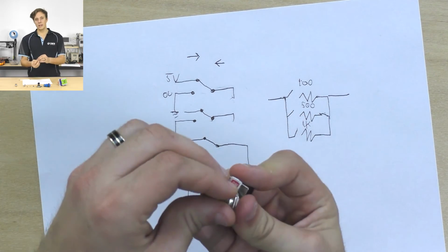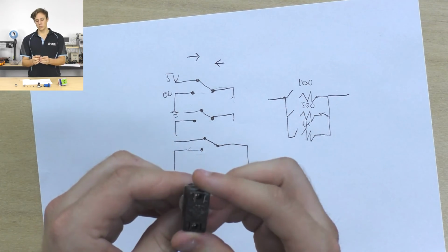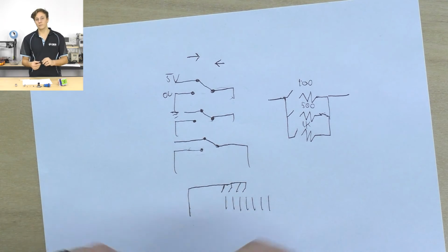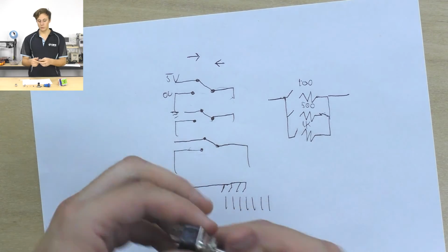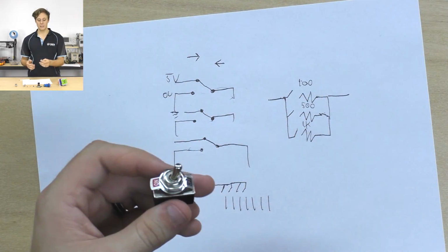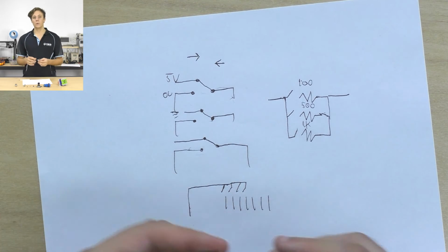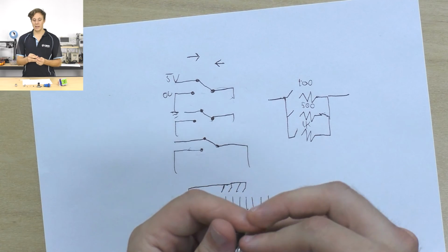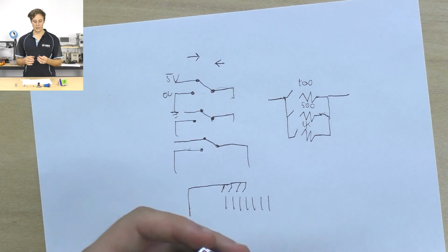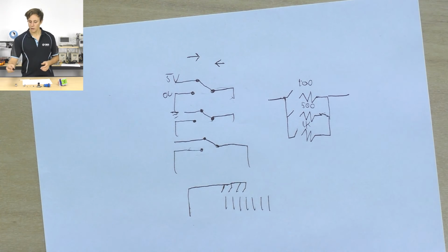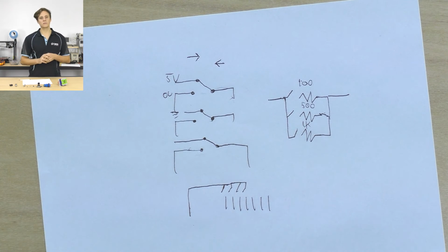And then lastly, your standard kind of toggle switch. Now this guy is a single pole, single throw switch. I can tell because there are only 2 contacts on it. It's going to be a single pole, single throw switch, and it is on or off. Generally designed as a trigger for things like control interfaces, or for master power switches, things like that, where you want a really clearly defined simple switch. So that's a few different types of switches and how they work.